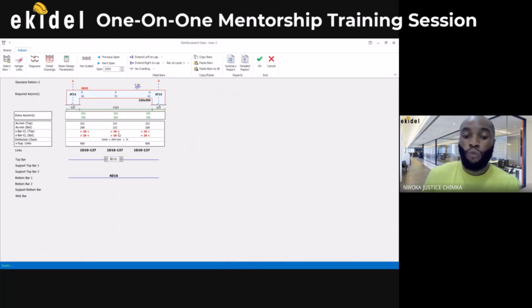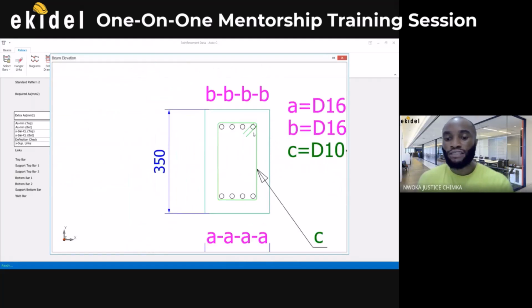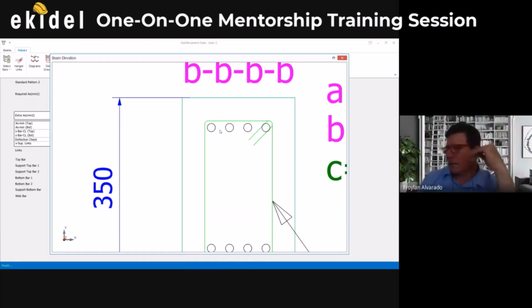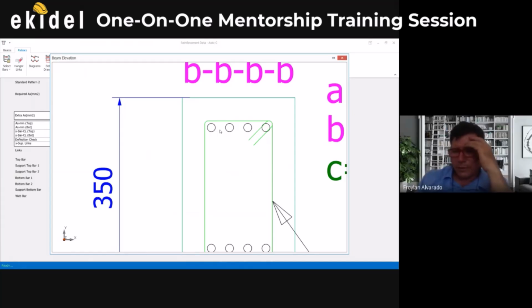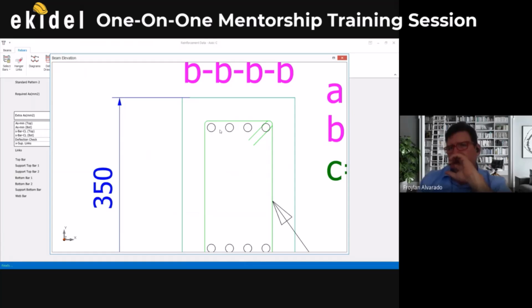20 millimeter. Now, why is that? If I open my drawing now, that spacing that you're seeing there is the spacing between these 2 reinforcements. So if the spacing is less than 20 millimeter, it will be hard for concrete to pass through, knowing that the maximum size of concrete chippings is 20 millimeter. That's, I think, 3/8 or something, or 3/4. Yeah, it's 3/4. So it means that if it is less than 20 millimeter.